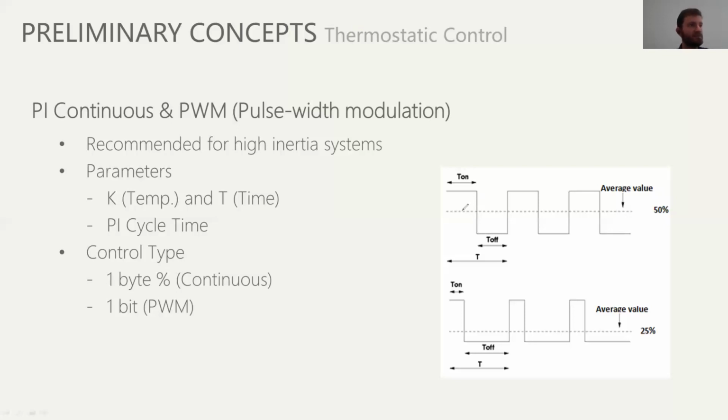here in both of these. This is a PWM where you have a 50% PI response. So I want to have the valve open for 50% of the time. So I turn on the valve during 50% of the time. My PI cycle time would be the 15 minutes we were setting before, and that's on.